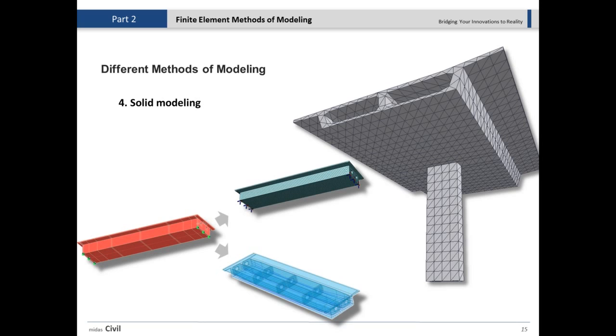result. And the good point about this conversion is that creating the model in Civil is very easy. It's 2 seconds. Then you can convert it into solid elements and quickly mesh it. And you can also convert the tendon profile, so you can transfer the tendon profiles into Midas FEA and combine them all together in the same model file, and everything is ready for you.